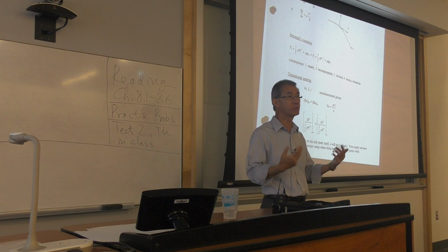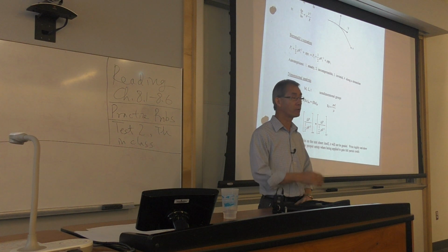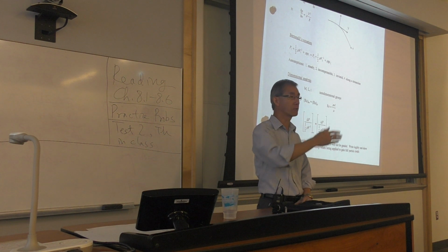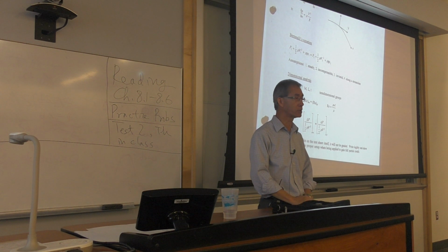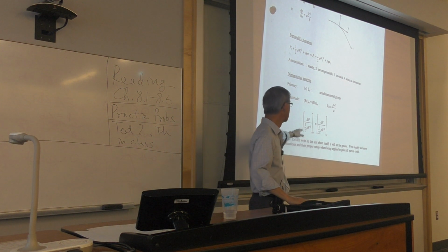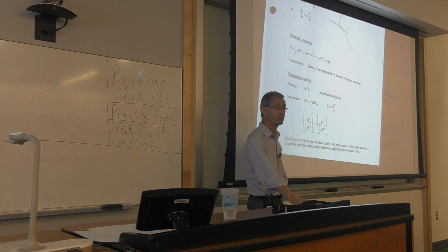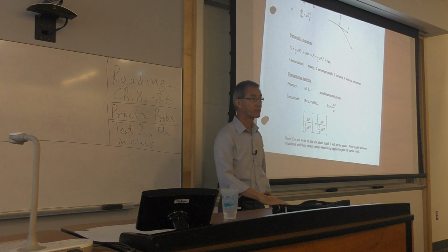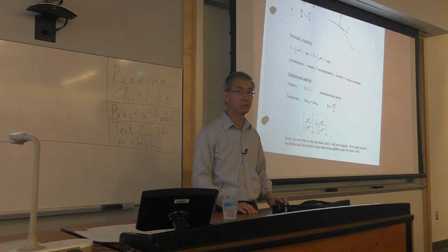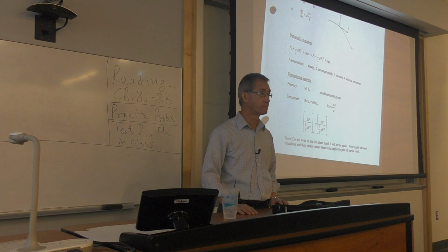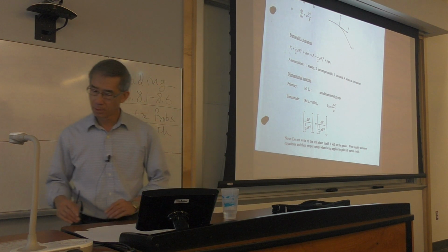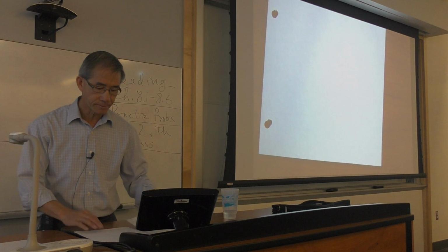It's the assumption we make as an engineer, just to simplify the problem, and very often people do that. They assume inviscid just to get a feel for the problem, do some sensitivity study, and then they add viscosity, and the analysis gets much more complicated, right? So to answer your question, if there's no viscosity involved, you don't even need a Reynolds number. But if there is a Reynolds number, this must hold. They must match. Otherwise, your model testing is totally irrelevant, right? Okay? Questions? Any more questions? Okay. So that's dimensional analysis.